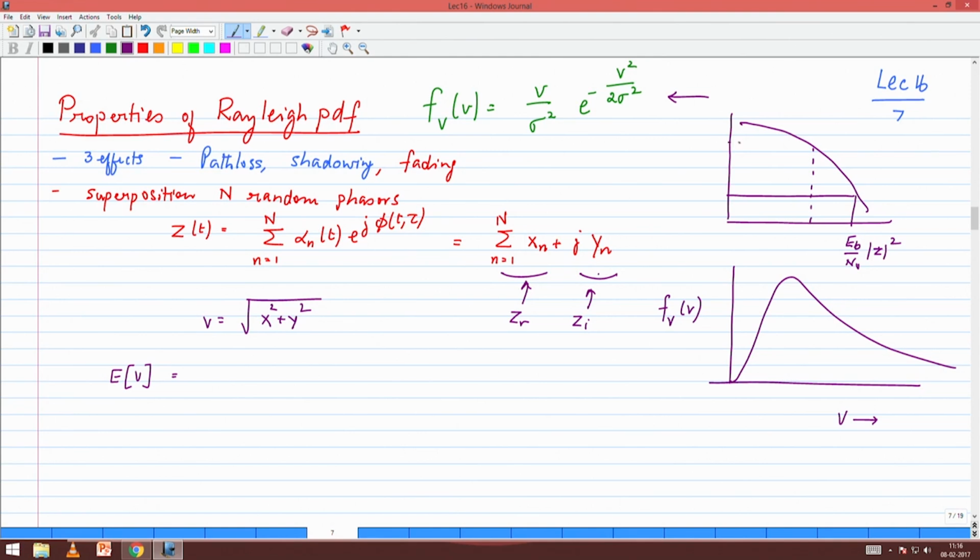All of a sudden, what was considered a good BER suddenly got perturbed to a very bad BER, because these BER graphs are very steep. A shift of 3 dB is very easy to happen in fading, but the BER impact is going to be totally unacceptable to you. So this is why we are very interested in the mean, the variance. Otherwise, we wouldn't care too much, since every distribution has got a mean and a variance, but we are focusing more on that.